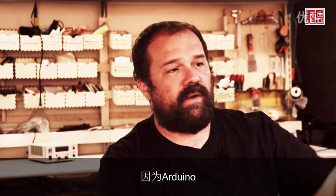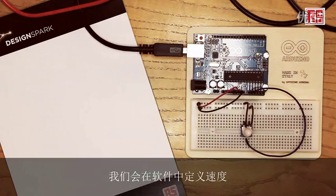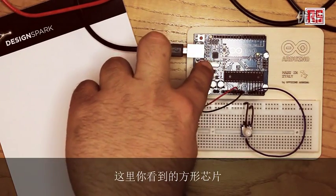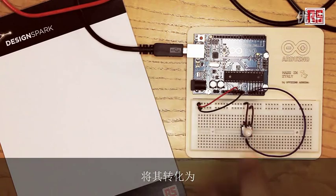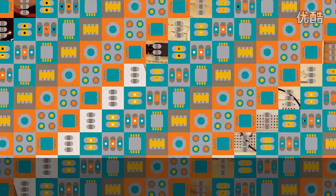So we're going to be using for this project something that's called serial communication, because the Arduino will send data over to the computer 1 bit at a time at a certain speed that we will define in software, and then the square chip that you see here will convert that into USB data that travels over to the computer.